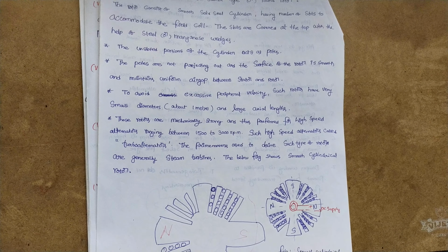double layer winding. The advantages of double layer winding over single layer winding are that it is easier to house the windings in slots during repairs. If any fault occurs in a synchronous generator, we can easily replace one coil. Another advantage is lower leakage reactance and therefore better performance. Better EMF waveform: a more sinusoidal EMF will be generated if we use multi-layer, double layer winding. It is also more economical.